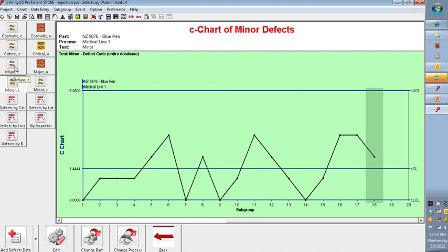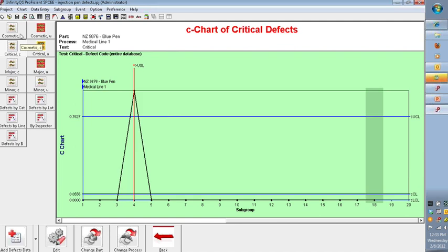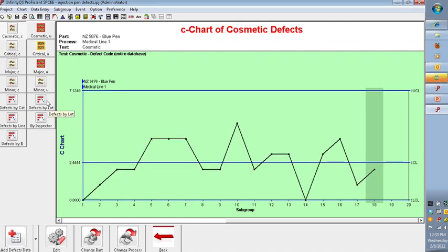Okay, so we've spent all this time seeing these control charts. One of the things, though, that I wanted to talk about next are all the Paretos I've got down here. Control charts are fantastic for telling me, here looking at cosmetic, I can see on average I get about 2.4 defects per piece. But this doesn't do a very good job of telling me which defects I have. Right? I had 3 points in a row here that each had 4 values in them, 4 defects, but were they the same 4 defects? Was it one defect reported 4 times? How can I get to that information? Well, that can be a little bit challenging from a control chart.